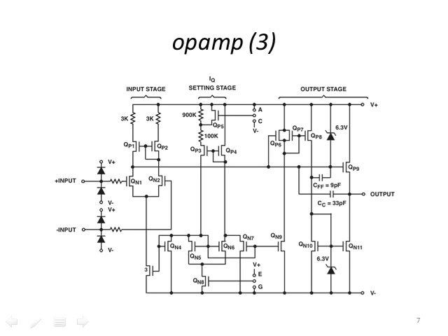And this is an example of a CMOS operational amplifier. Again, it has the same sort of blocks: the input stage with the differential input, with our inverting and non-inverting terminals. The biasing stage, as it's labeled here, basically the current mirrors to be able to set the current for our amplifier units.